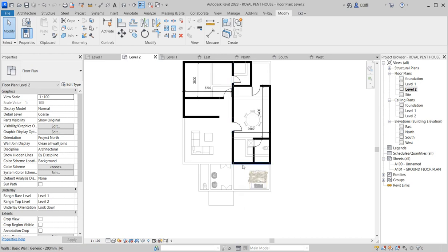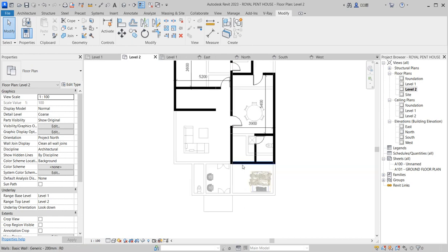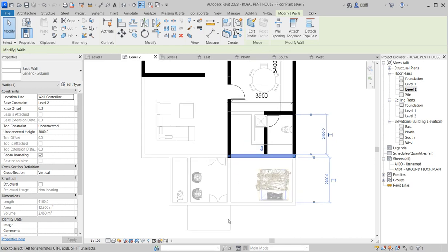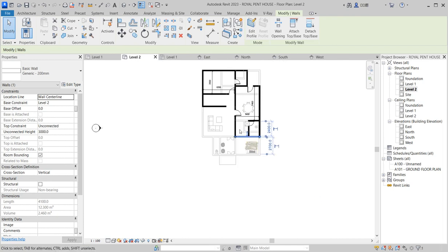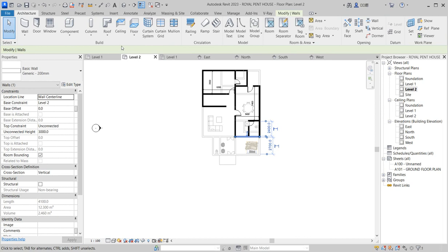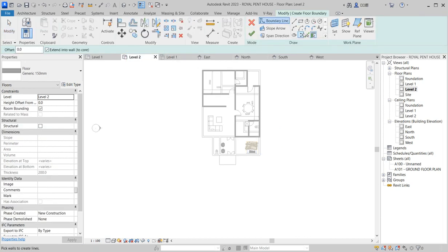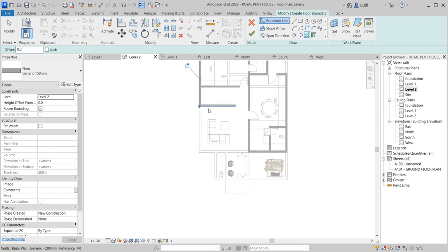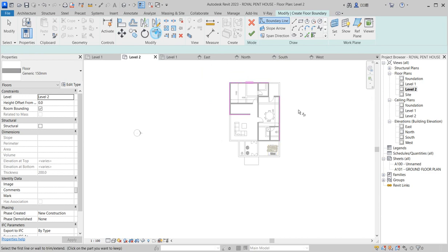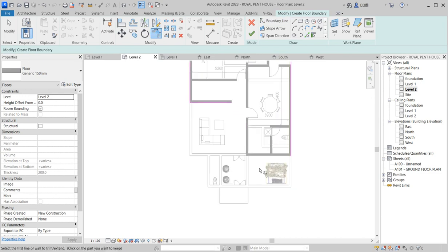So the balcony is going to take its own shape from the rear view of the anteroom. So what do we do? We first create the slab in this position. So click architecture, then click slab, so that you know what to work on and what we are not working on. So the slab is created in this manner. Create the slab, and put it there like that.